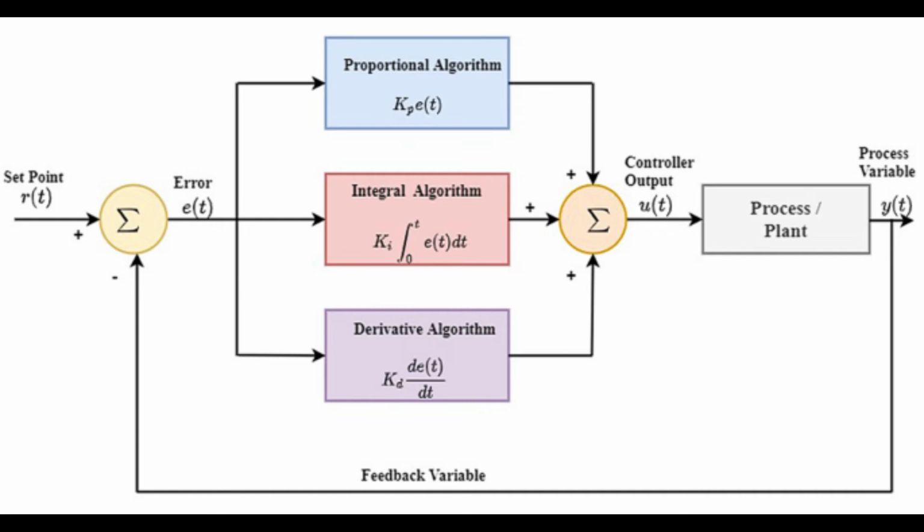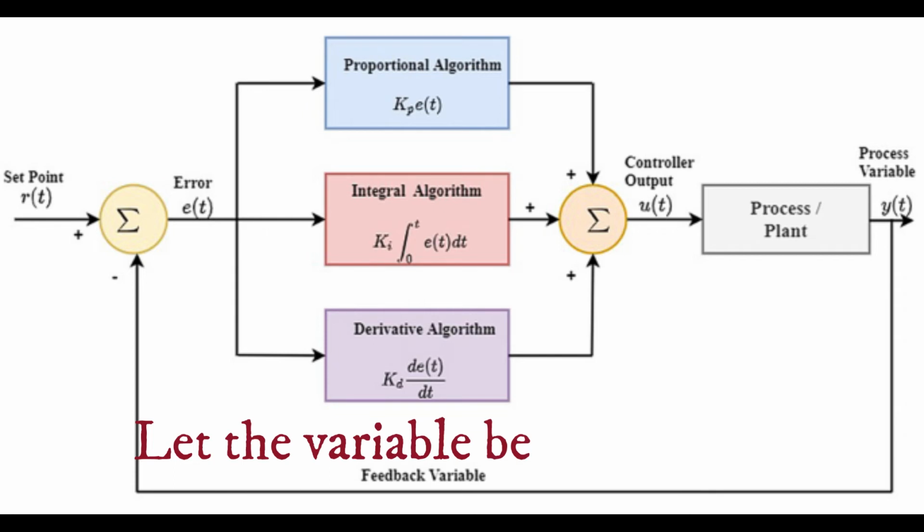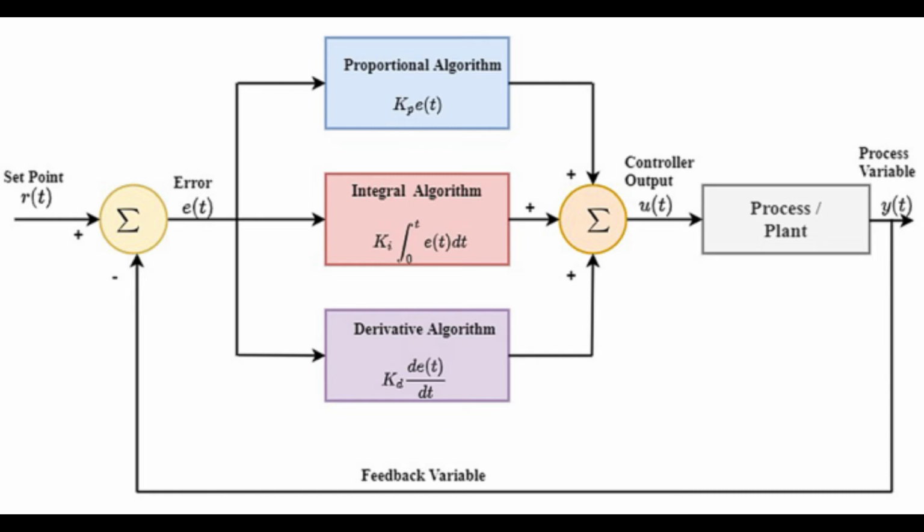This means that we have to add the value of error function in each step to a variable, say sum, and we have to use this overall sum of errors to multiply with Ki for our integral parameter. In other words, our drone will oscillate across the given space coordinate until it finally stabilizes.